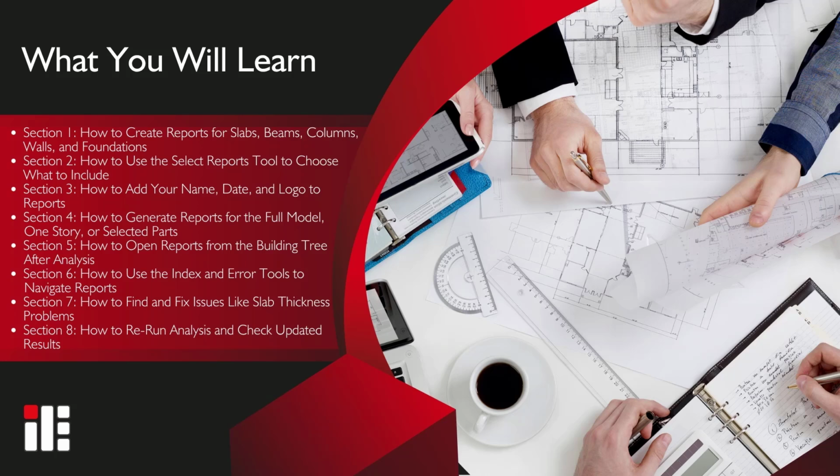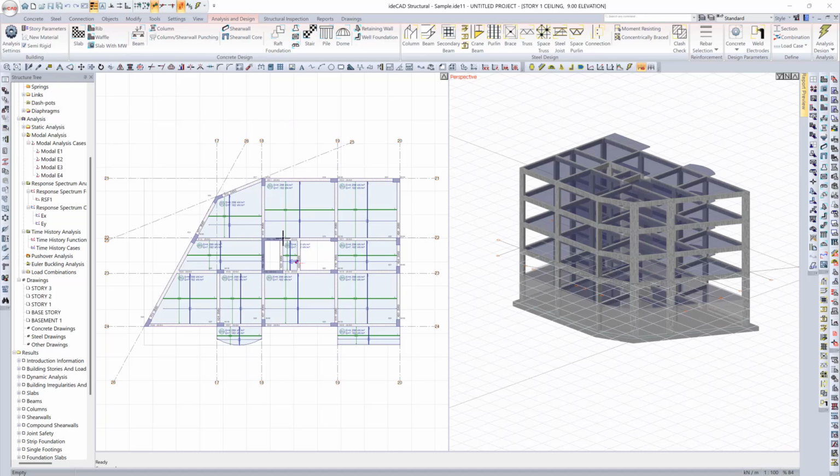You'll also learn how to open reports from the building tree and quickly find errors using the built-in index and navigation tools. Then, we'll use those reports to fix design issues, like slab thickness problems, and rerun the analysis to check the results. Finally, you'll explore special reports for dynamic analysis. By the end, you will confidently know how to produce and use reports to improve your modeling workflow.